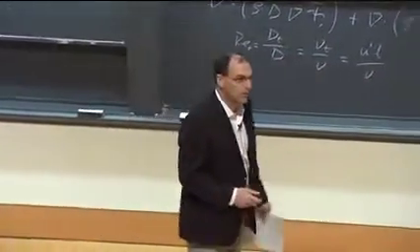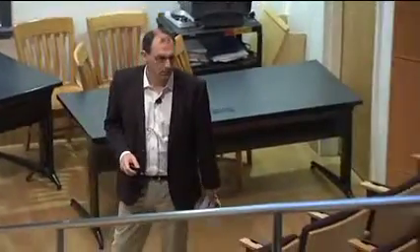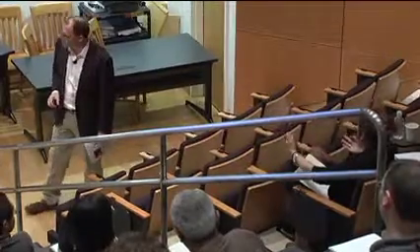The gradients, the actual value of the gradients, when you solve it, would be equal. However, in a physical way, these gradients aren't taken in the small scales because it's very small. Yes. That's large, right. Exactly. But so what you're saying is the local instantaneous gradients in a turbulent flow, they're much larger. But they don't appear here.